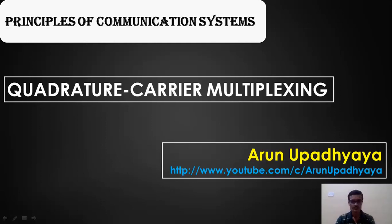Hello everyone. In this video, I will explain a concept called quadrature carrier multiplexing. As you know, multiplexing means transmission of multiple signals through a common channel. Now in this quadrature carrier multiplexing, what exactly we are doing is, we are transmitting two independent message signals by modulating using the same carrier, but the carriers applied are in phase quadrature. That's why it is called quadrature carrier multiplexing.